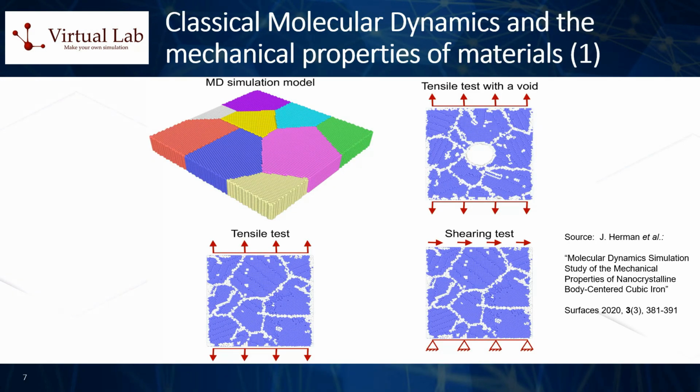Let's now describe the alternative case of how classical molecular dynamics computational techniques can be used to compute the mechanical properties of materials. Molecular dynamics, MD, is a computer simulation technique that models the physical movements of atoms and molecules. The atoms and molecules are allowed to interact for a fixed period, giving a view of the motion of the atoms. In mechanical studies, molecular dynamics is used to simulate and study the mechanical response of a material at the atomic scale. Here's how this is typically done.